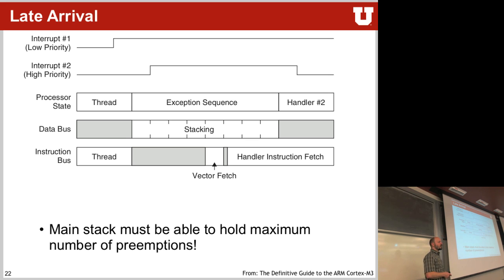So it does finish stacking from the first interrupt? It's the same thing, right? Because the stacking takes the main program and puts it onto the stack. There's nothing it has to go and fetch for the interrupt service routines, except the location. And as long as this vector fetch hasn't happened yet, it will fetch the one of the higher priority.